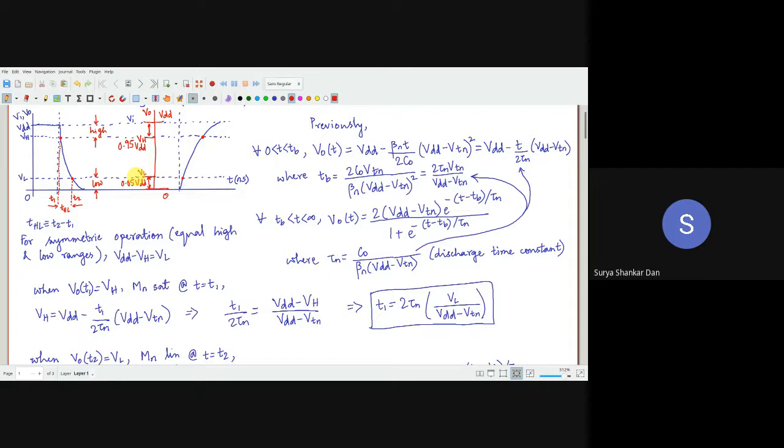Since the industry in general has accepted this 10% of VDD variation, when we compare two or three different ICs and want to find out the delays, rise time and fall time, we go by 10% for all the ICs, and then we can have a fair comparison.